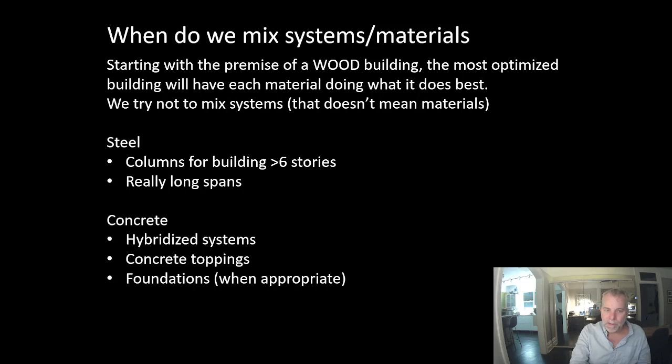Hybridizing mass timber and steel is extremely common. The academic wood tower, our central core is steel. That was a major concession in order to get the tall building, is that the core had to be non-combustible. So the core is steel, wood around it. Limberlost Place is the same. When we get into tall buildings, we would often use steel columns or concrete columns as opposed to mass timber columns, just because mass timber columns get really massive. They start eating up a lot of real estate.